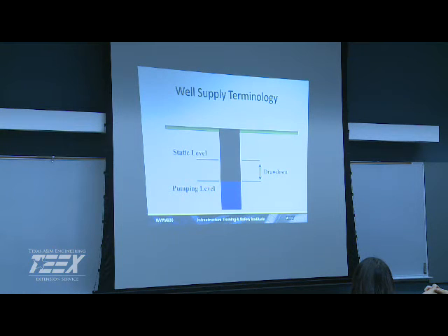If you have a real strong artesian, you're probably going to have very minimal drawdown. Maybe if you're running constantly for a long time you might, but you probably don't even need a 5-horse to get water out if it's that close. This one we just use like 1.5 horsepower. Your pump might be that far down, but the water in your casing is up really close to the surface, so it takes almost nothing to push it out, which is a blessing.